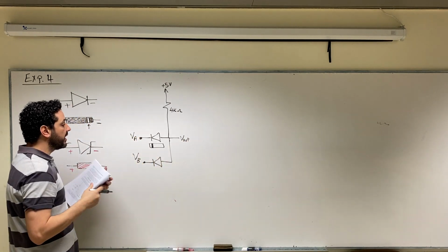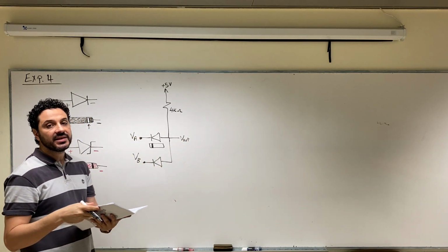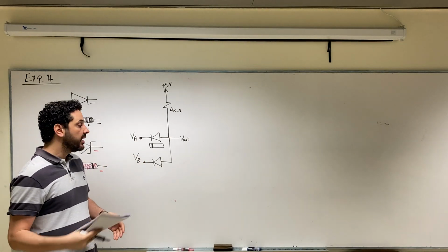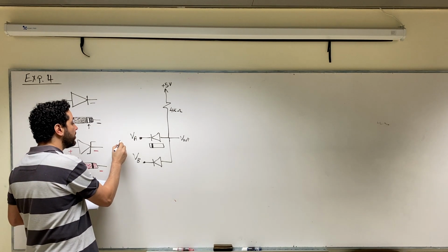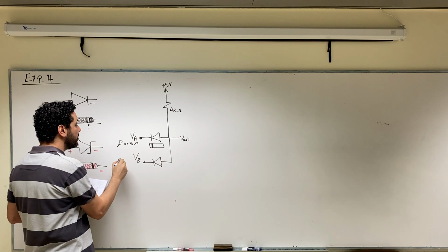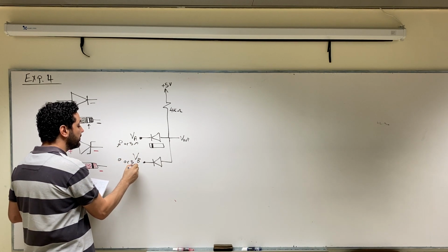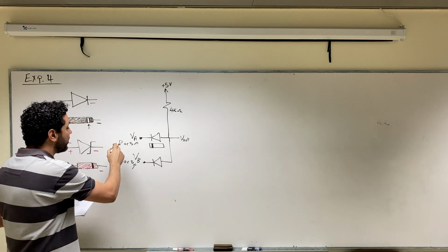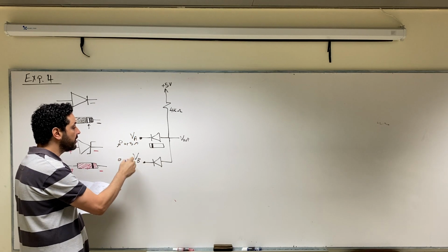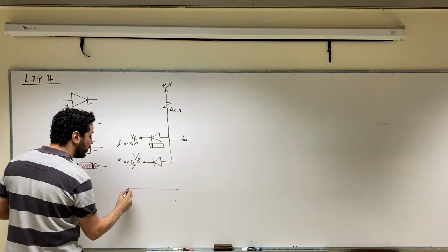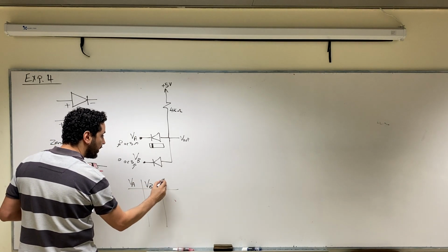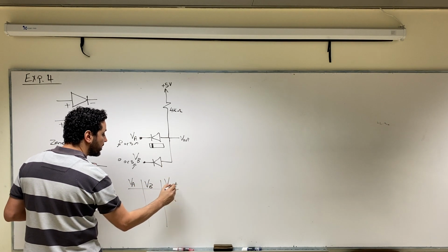The voltages that we are connecting here, VA and VB, are DC voltages, so we are going to use the DC sources attached to our board, and we are going to connect either 0 or 5 for VA and 0 or 5 for VB. One time we connect 0 and 0, or 0 here and 5 here, or 5 and 0, or 5 and 5. And then we are going to build a truth table. And in each case we measure V out.